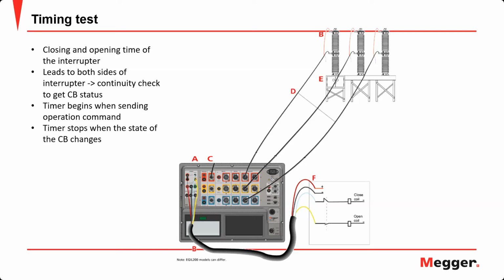It is done during the production of the circuit breaker to check that the operation of a new CB is within the speed range selected during the development of this specific type of circuit breaker. It is done also during service as a part of routine maintenance to determine whether it is still operating correctly.